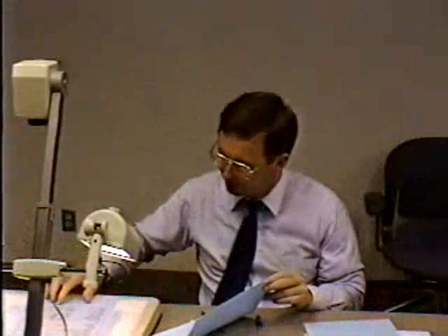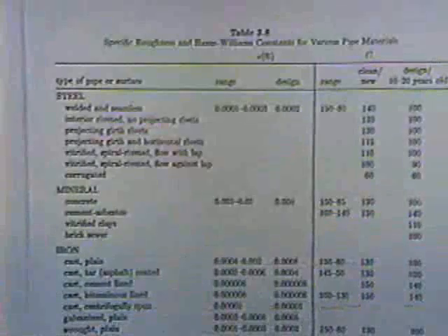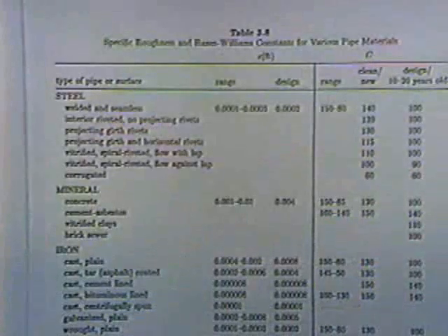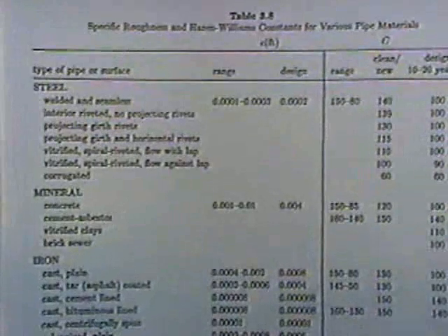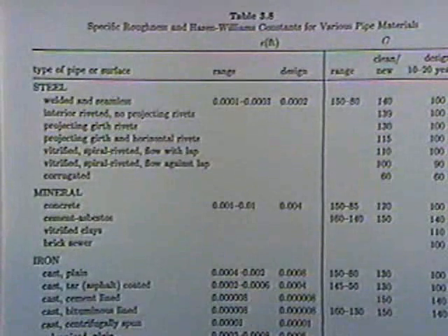There are tables in all the references. This is the table that I Xeroxed out of the Civil Engineering Reference Manual, which you're using in conjunction with the review sessions. And for different types of pipe, it gives the values for roughnesses. And again, the physical meaning of this roughness is, of course, the roughnesses in the wall of the pipe vary, but it's sort of an average effective type of roughness height, distance measured from the wall of the pipe.